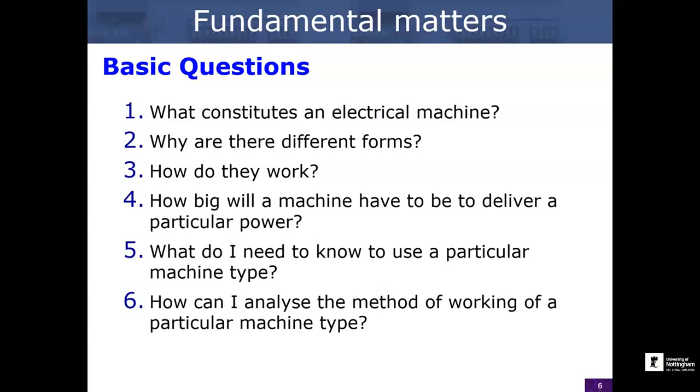So in an electric vehicle, you may have 4 machines, one on each wheel. You may have multiple drivetrains. You may have combustion systems and electrical systems working together in a hybrid. But you need to have ways to represent those on an abstract level as an electrical circuit so that you can have something that shows you what kind of power goes in, what kind of power comes out, and you can start to build those into an overall system model so you can apply them.